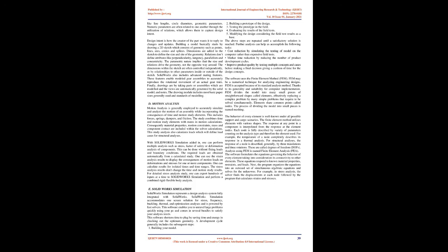1. The Scorbot ER-V Plus is a 5-DOF vertical articulated robot and all the joints are revolute. The kinematics problem is defined as the transformation from the Cartesian space to the joint space and the other way around. The Denavit-Hartenberg (DH) model of representation is employed to model robot links and joints during this study, alongside a 4x4 homogeneous matrix. Scorbot ER-V Plus is a dependable and safe robotic system designed for laboratory and training applications too. As for the links of a robot arm, the Denavit-Hartenberg (DH) coordinate transformation method is usually used.